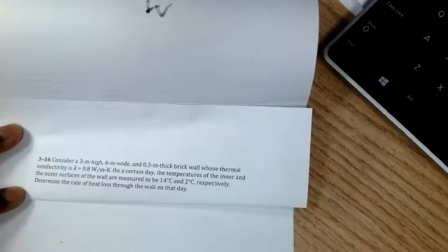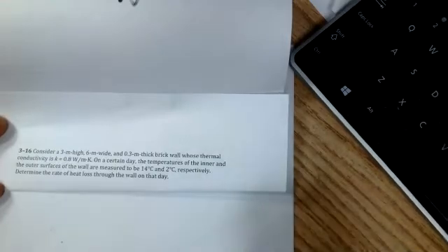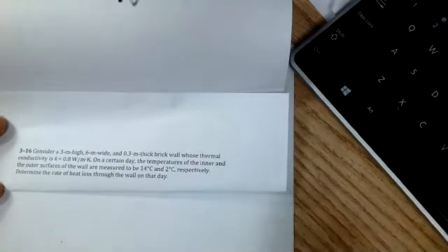Okay, so from initial examination, this is a conduction problem through a wall. And as we talked about last week, conduction can be considered in multiple ways. So the first thing you have to think about is, am I being asked to solve a multi-dimensional question? Is this a transient or steady state problem? Is the thermal conductivity constant? Consider these three factors before you move ahead.